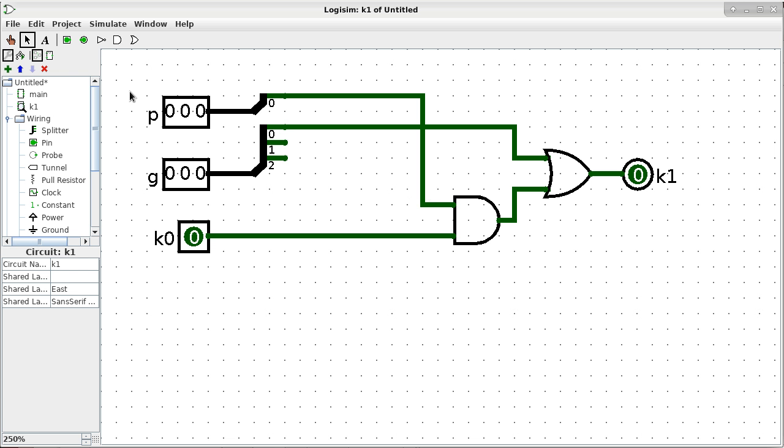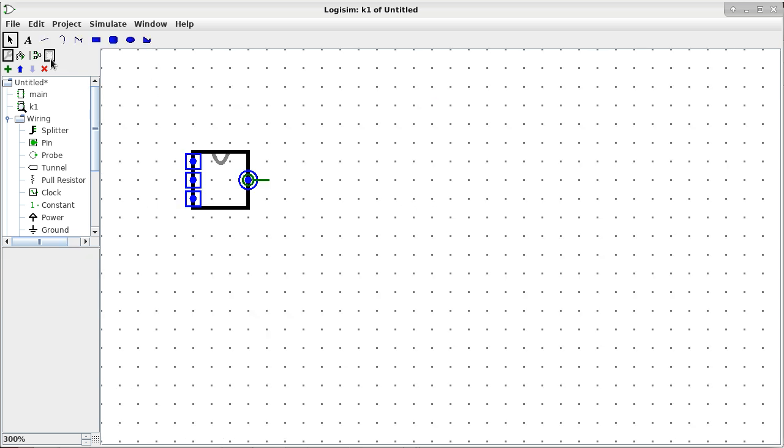So let me switch to the appearance, which is here. This is the default, and it picks up the pin positions based on the position of the pins inside the design. But if you have moved things around after you have edited the appearance, then the appearance will stay the same while the inside of the definition has changed. So that can cause confusion.